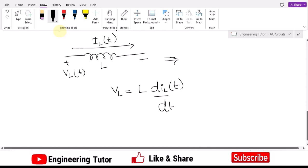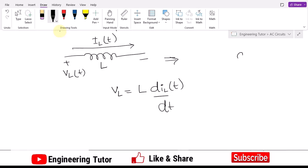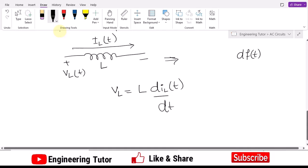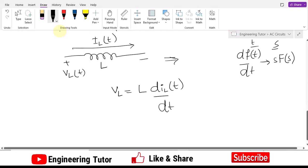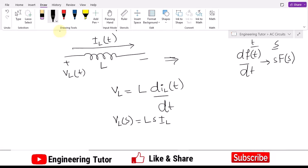Similarly, we have also seen that in converting the derivative d f of t divided by dt from the t domain into the S domain, the derivative term will be replaced with S, while f will be replaced with F of s. So this will be the conversion of any derivative term. Now taking the Laplace transform of this function, I will get V L of s equal to L, the derivative term will be S, and the current will be I L of s.